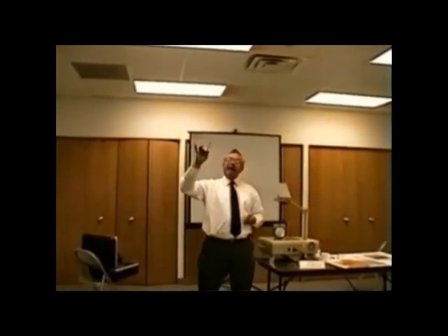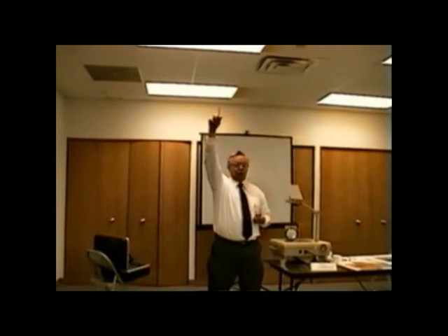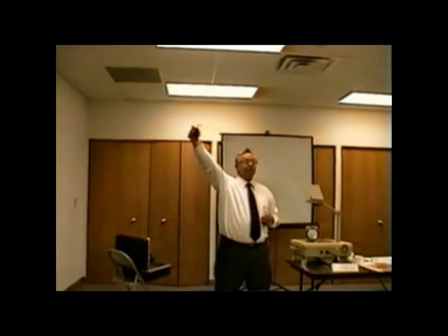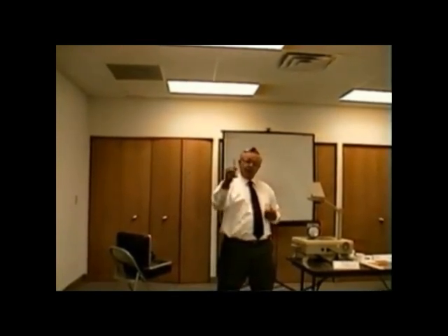It's external to the furnace and nothing else. When we say external to the furnace, that means you take your probe and you stick it in the supply under the coil. That's external to the furnace. If we go beyond the coil, now it's external to the coil, and it won't give you the right reading. We want to know how much air is going across that heat exchanger, because whatever's going across that heat exchanger is being supplied to the A coil. Okay? So the point is this, we stick this under the coil.